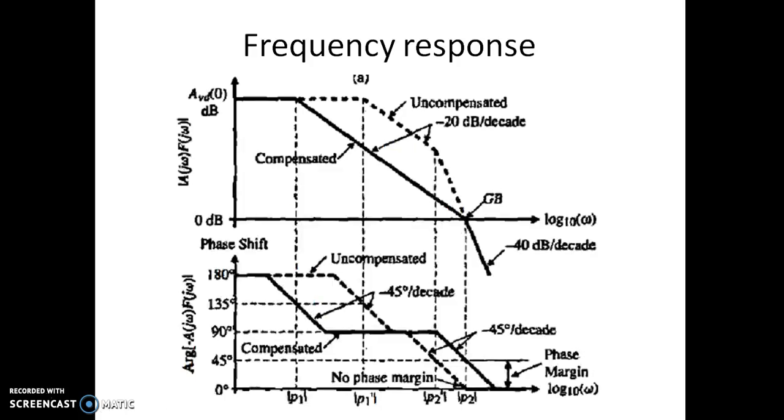This is the expected frequency response. Since the circuit is a compensated one, we are going to get the frequency response shown in the solid lines, having its cutoff frequencies at omega P1 and omega P2 here.